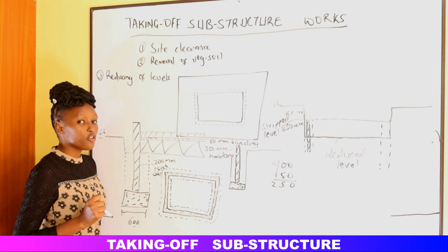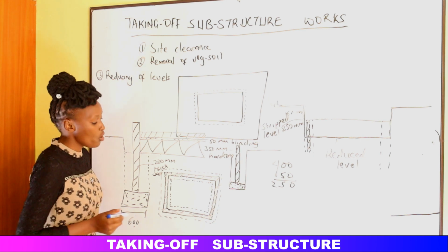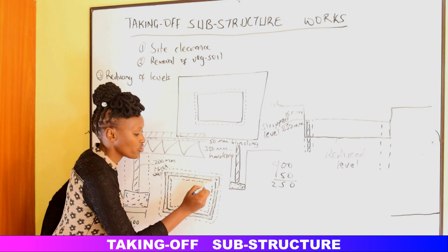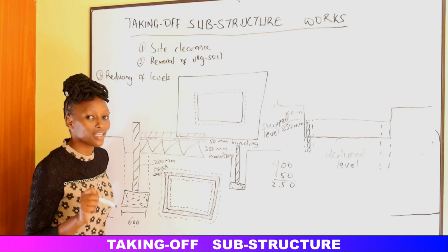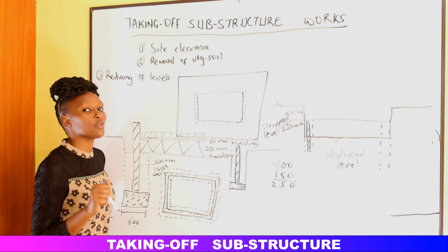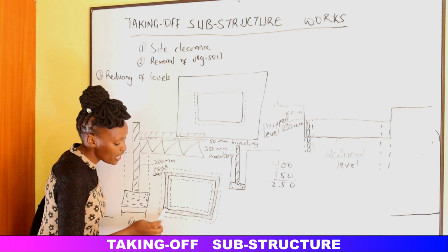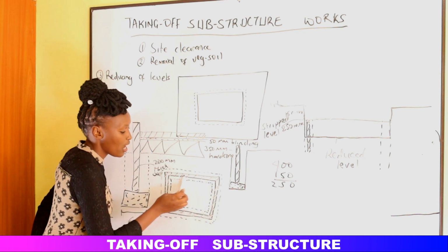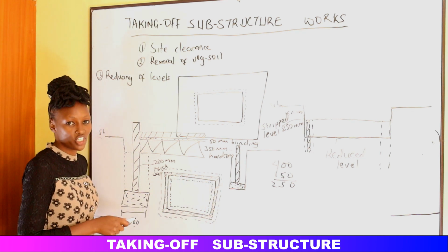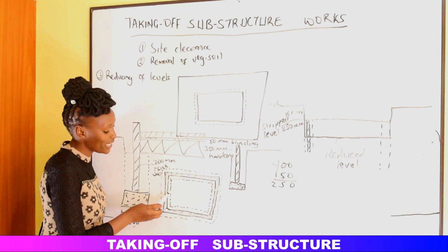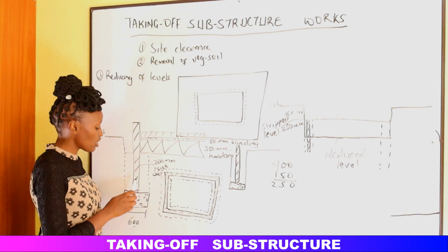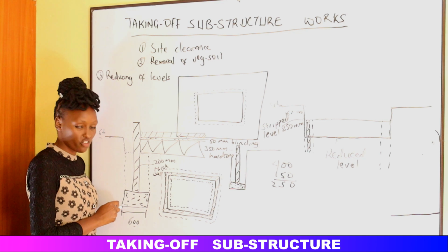When we are finding the volume we shall excavate for the soil, we shall take the center line of the trench, which is the same as the center line for the wall, because the wall is positioned at the center of the trench. So we shall take this total length of the center line of the trench, then multiply by the thickness of the trench, then multiply by the depth of the trench.